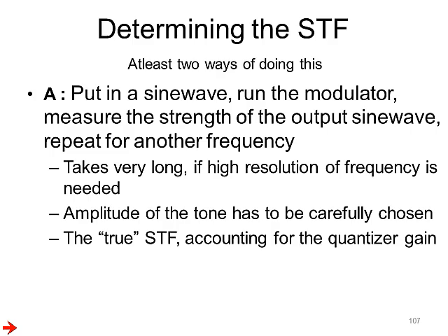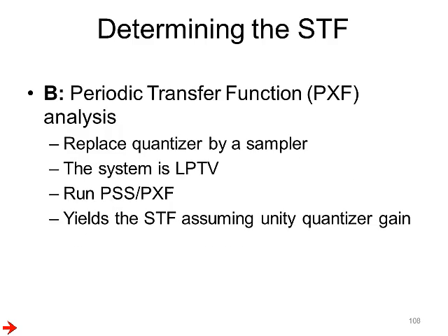However, the advantage of this is that you get the true signal transfer function, which accounts for the signal dependent gain of the quantizer. Another way of doing this is to use the periodic transfer function analysis.